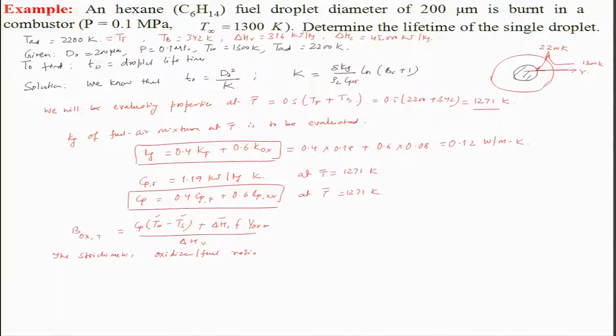Okay, the oxidizer fuel ratio you can write down as nu, which is equal to (x plus y by 4) divided by 4.76, times the molecular weight of air. You can do it the other way around also; this is a direct formula I am using, and if you substitute these values you will get 15.16. That means F will be 1 by nu, which is nothing but 0.0658, right.